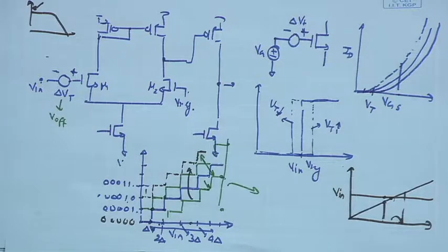Any other question? So, as we have seen in the chopper, what are we trying to do? We are trying to shift the signal towards higher frequency. The 1 upon f noise is towards DC, close to DC. We do not want it to interfere with our signal. So, there also we are trying to model that noise with a very low frequency source close to DC.